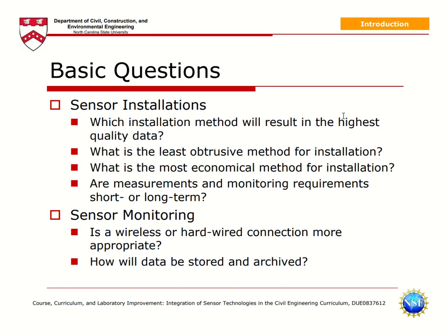And the second question would be, how will the data be stored and archived, right? For the monitoring purpose, you need to identify how and where the data will be stored as well. And whether a wireless or hardwired connection is more appropriate. You have to identify the appropriate connection for that sensor.